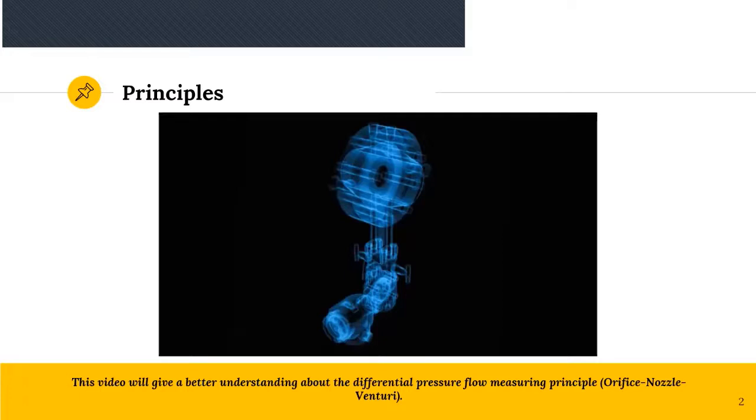The orifice is just like a mounted plate that is welded in between the flanges, so it has no nozzle. The change from the larger pipe to the smaller one is very sudden, so it will increase the eddies and also turbulence.